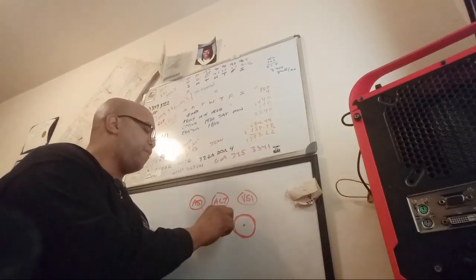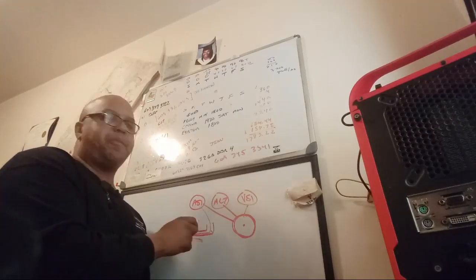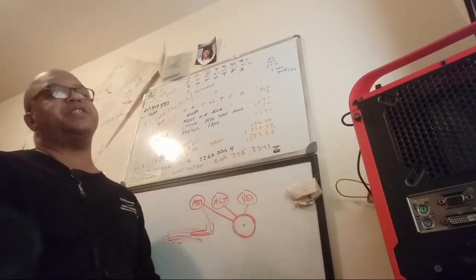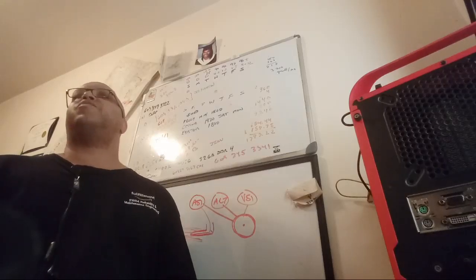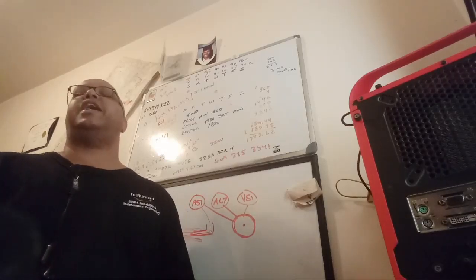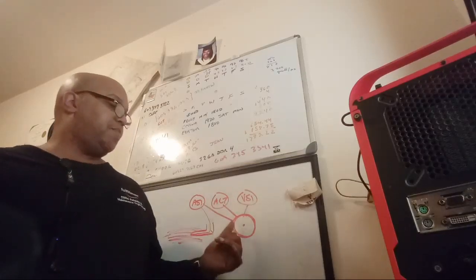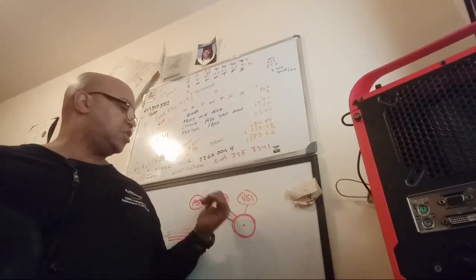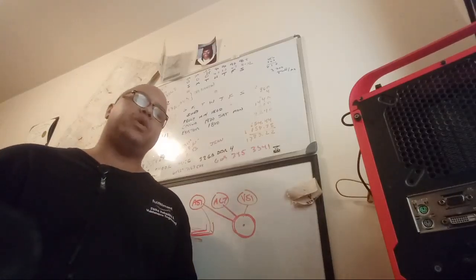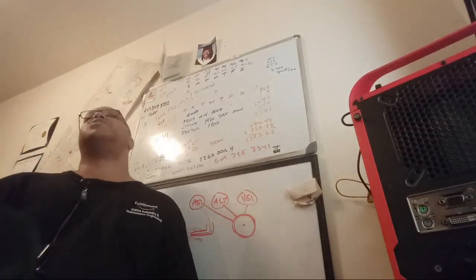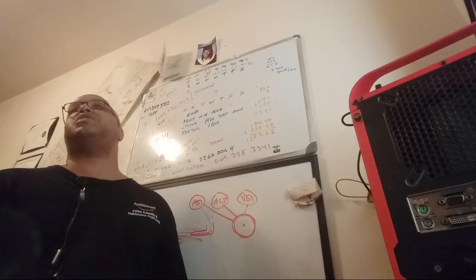Now the static port feeds all three of these. The ram air or the Pitot tube only feeds the airspeed indicator. That's it. All right. Ram air only goes to the airspeed indicator casing. The static port is connected to all three. Now we'll go in depth with how an airspeed indicator works down the road a little bit here. But that is the Pitot static system.